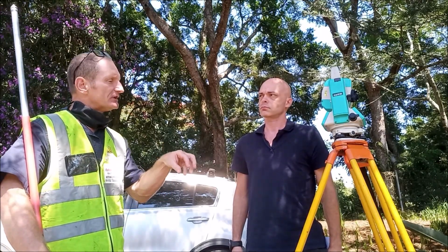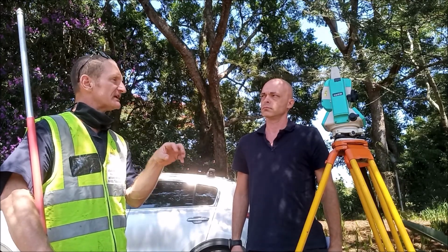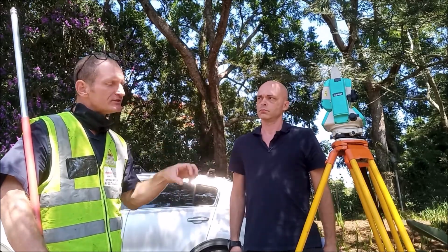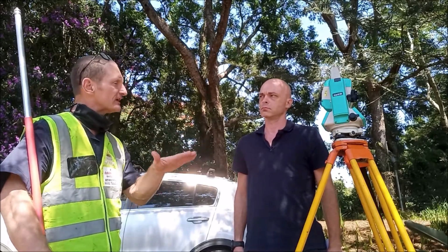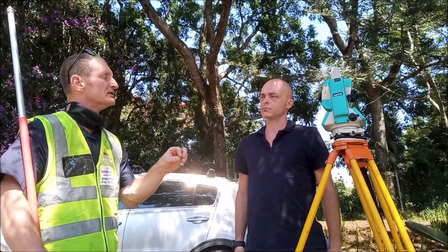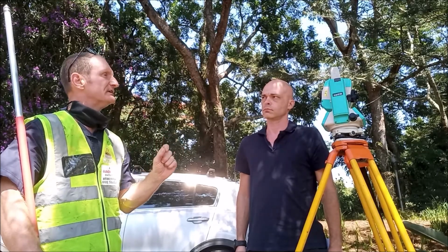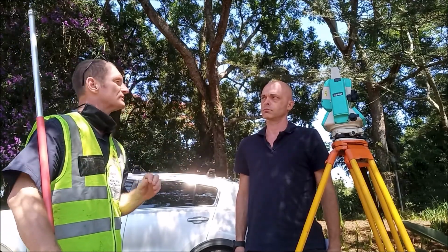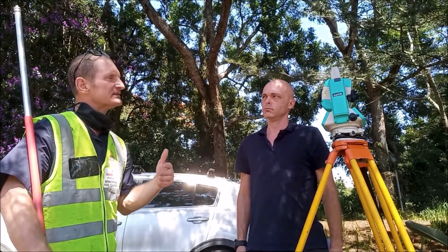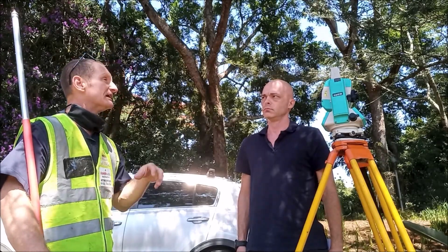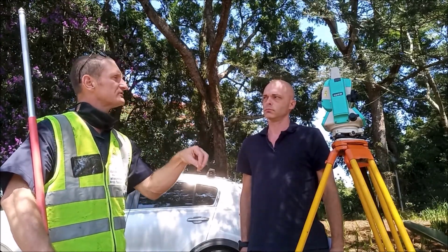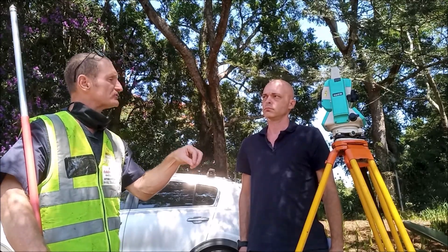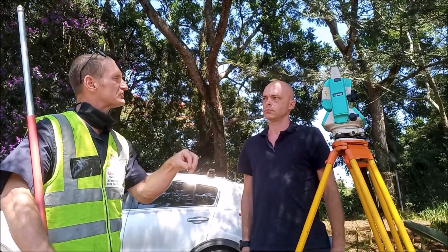Now, that position is generally known in the vehicle, but in order to get that accurate, we would need to have the vehicle set up on a set of corner weight scales. We'd need to know the distribution of the weight, and then through knowing those and through certain procedures on the corner weight scales, we can quite accurately determine the center of mass of the vehicle, and those values are then applied into a calculation that would allow us to determine things like the static stability rollover factor. It is also allowing us to determine the center of mass position of the vehicle when we're applying that in momentum calculations, so that we know we are applying to an accurate position on the vehicle.